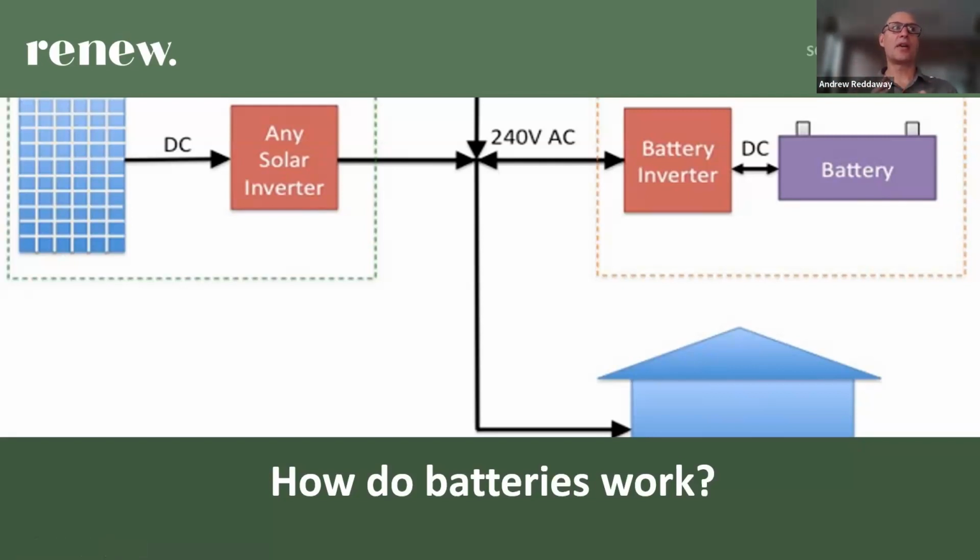And the way the electricity rules work is, as soon as you go messing with something, then oftentimes you have to bring the whole thing up to current standards. So once the solar installer starts doing something to that old system, then they might find they have to replace the cables and the switches and the conduit that the cable came in, and you end up replacing the whole system basically. So yeah, doing it this way with a battery with its own inverter can often make pretty good sense.